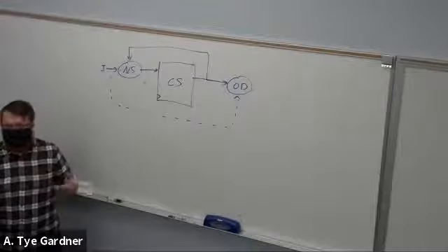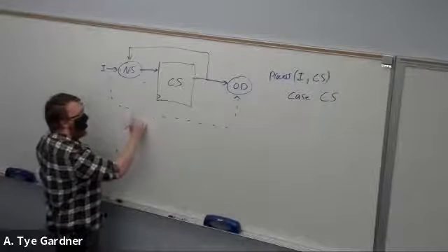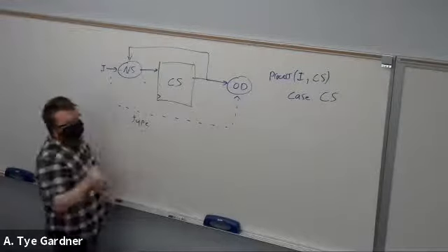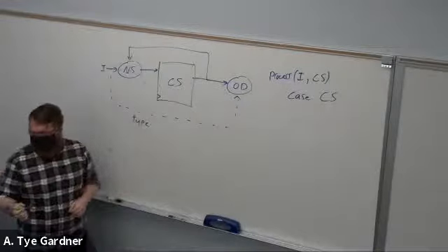Then we go to the heart of our state machine, which is a case statement, right? And we always case on where we are now. What is our current state? Now, remember, we want to create a signal for current state. We could do this with a standard logic vector or even bits, but it's easiest to use what we call an enumerated type. Just like we have the type for standard logic vectors, and types for bits, we're going to create an enumerated type.